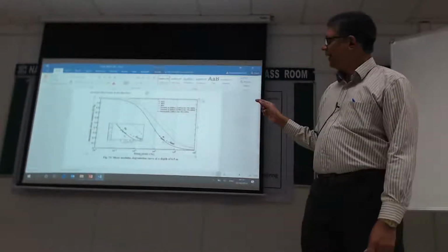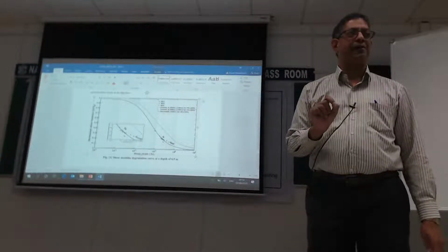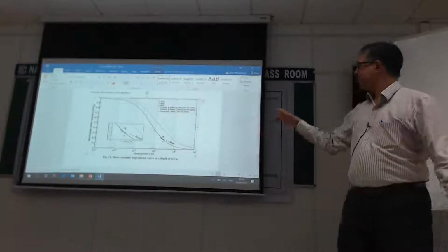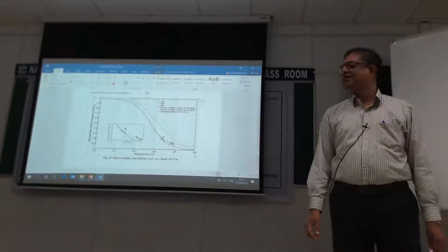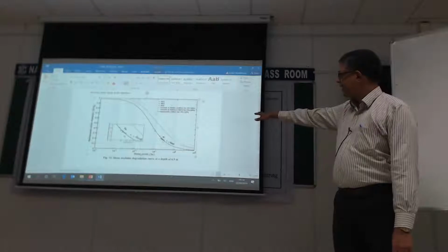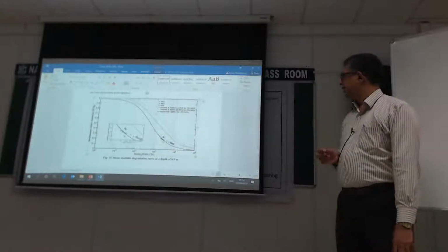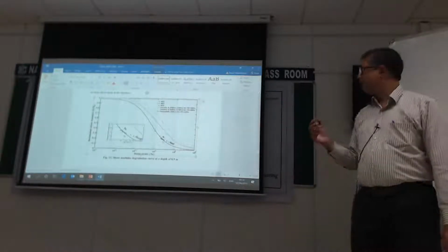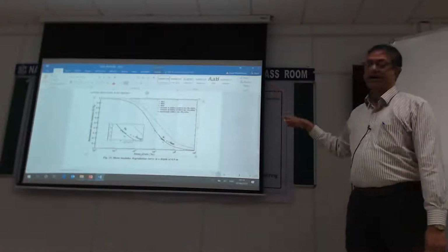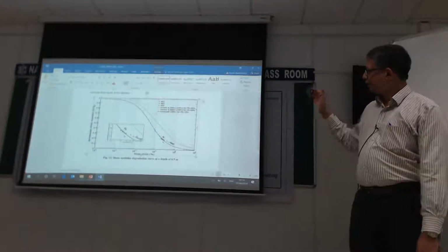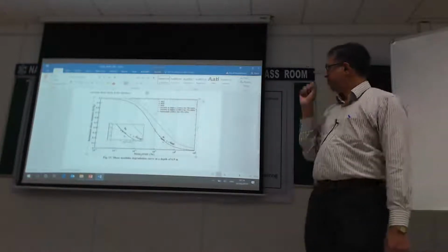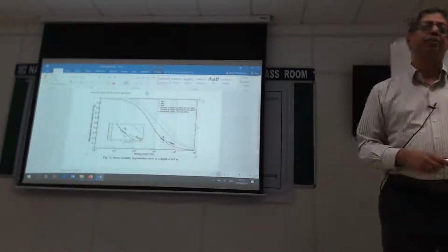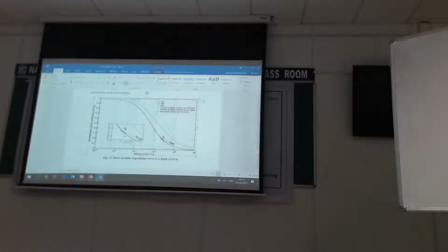We can plot our points from the experiment onto these for different depths. Here is one for a depth of 6.9 meters, and you can see our strains are between maybe 0.03 to 2.2 percent, and you can see how much degradation we got. You can compare with methods existing in the literature, very well-known ones like Vucetic and Dobry or Darendeli curves.